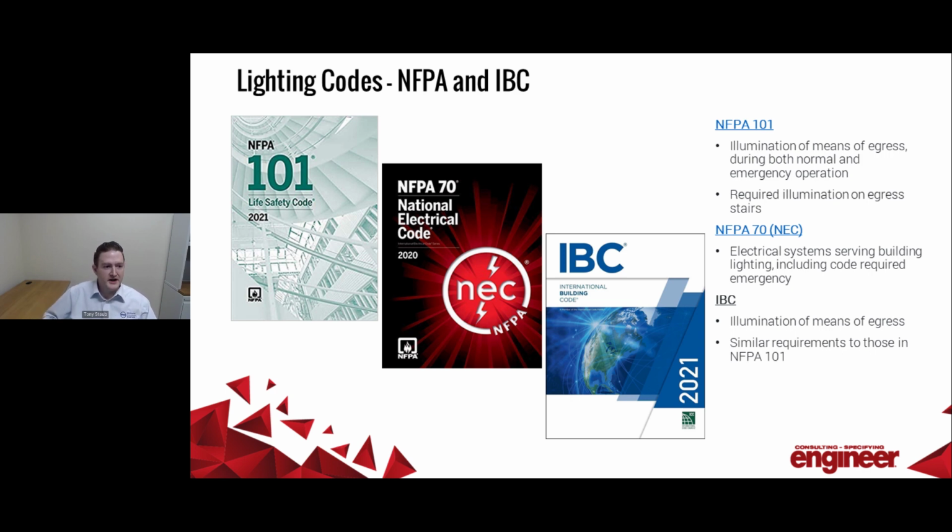So depending on what type of building you're in, I personally do a lot of healthcare engineering. And in healthcare, we are looking at 517 a lot, where there are very specific requirements about what lighting can and should be placed on the life safety branch, on the critical branch, on the equipment branch, and on the normal branch. So it's really telling you how to organize the circuitry for your lighting.